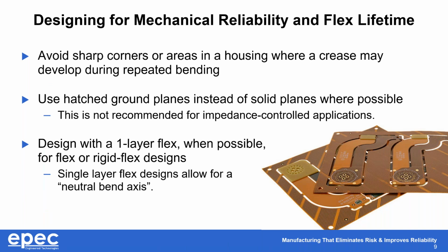And then when possible, for both flex or the flex area of a rigid flex design, use a one-layer flex. The reason is you can design a stack up such that the copper is in the middle of the stack up. It allows for a neutral bend axis, meaning the copper is not being stressed in one direction more than the other.